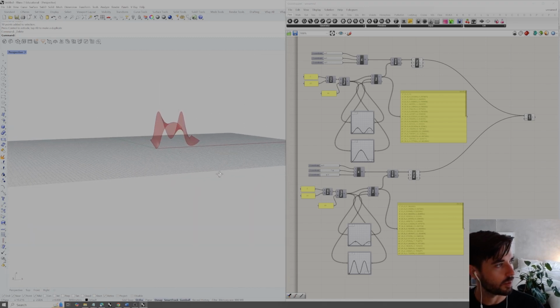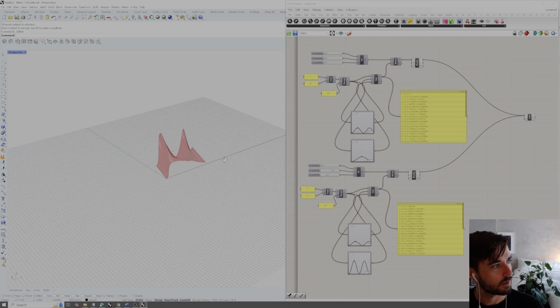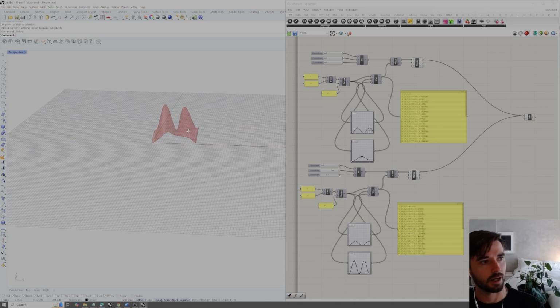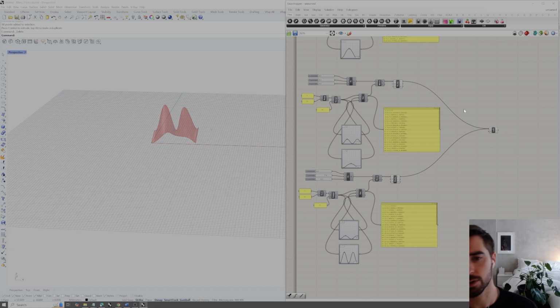And it's still going to be performing that loft operation. So you can see that kind of parametrically lofting these 2 curves that we're feeding in. Alternatively, you could perform just a move or some operation to transform or translate one curve and then plug both of those in like we did for the point at the beginning.